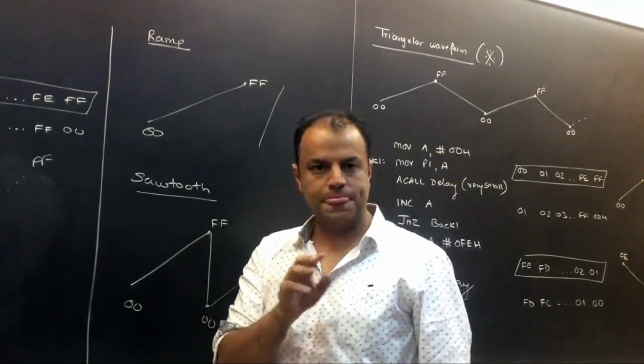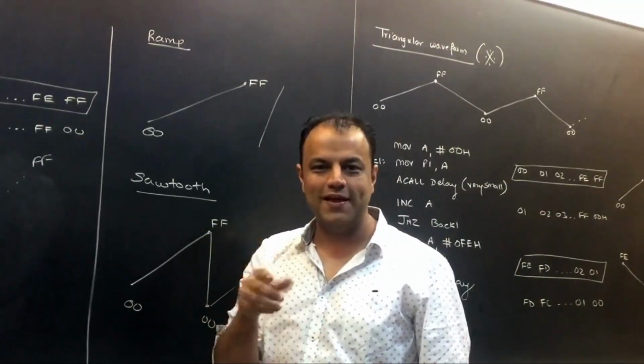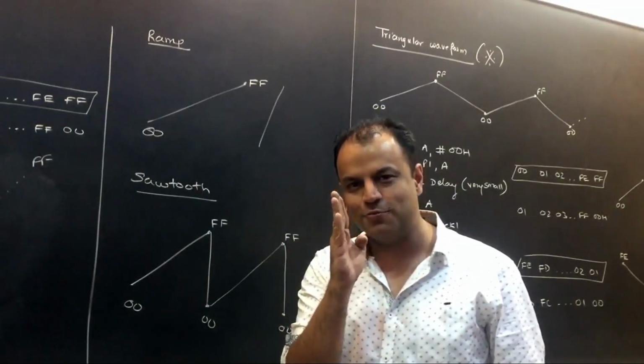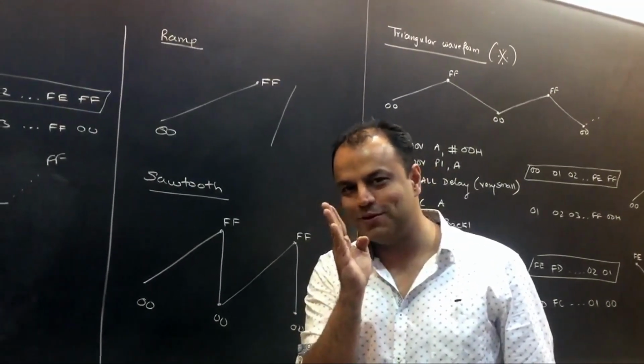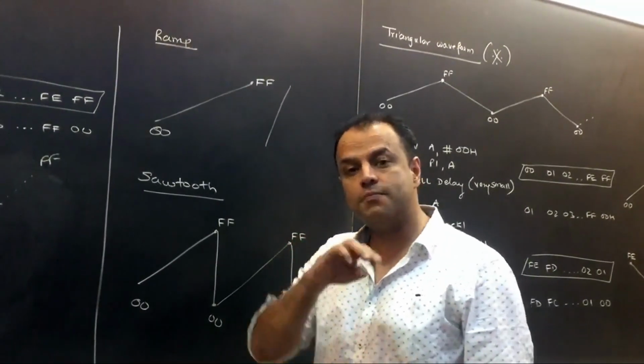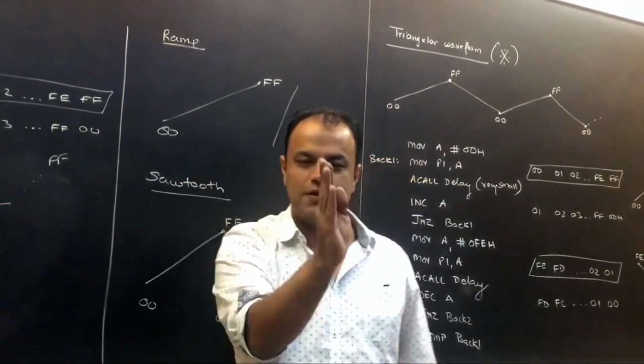Put a delay, not a very big delay, 1, 2, 3, 4, 5 milliseconds. Again, this is all plain. Put a delay of 1 millisecond and see what happens. You will start seeing a slight slope. Put 2 milliseconds, even more slanted. 3 milliseconds, more slanted. 4, 5, till the point you will start seeing it break. Once you start seeing it break, stop it, go one step back.